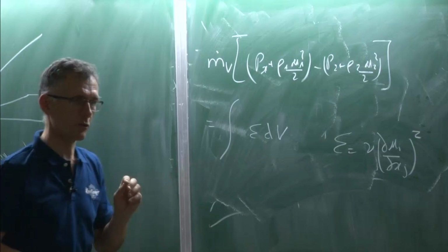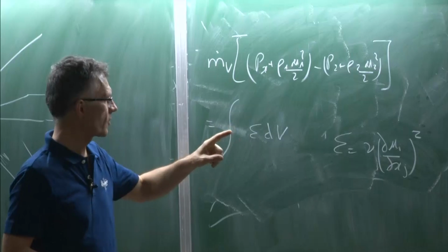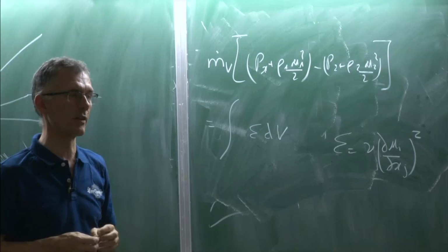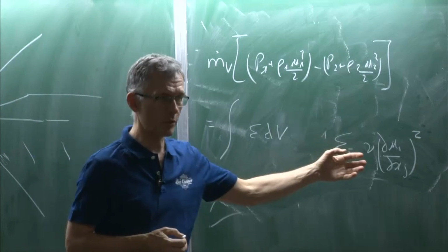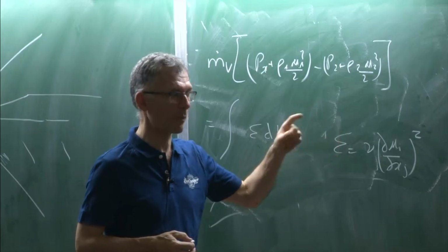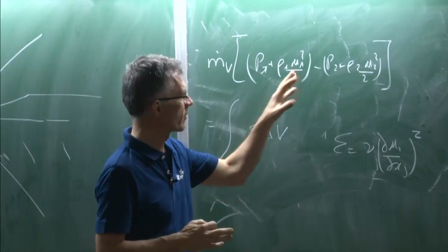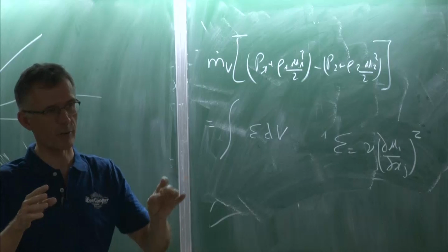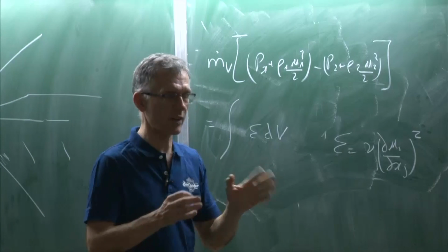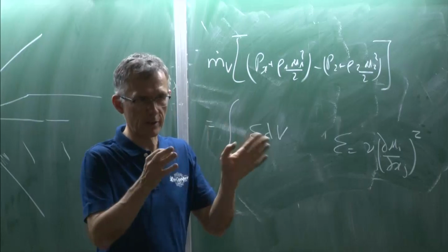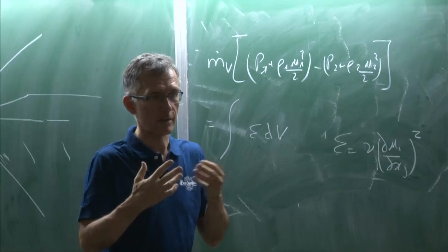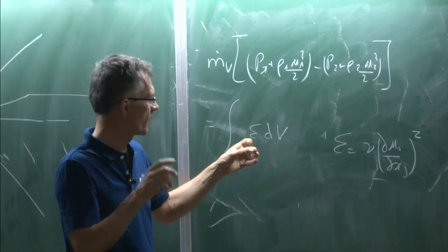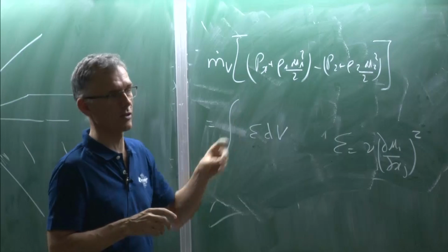And so the metric that you should use is epsilon. If you want the right pressure losses, the equation tells you that the field which must be resolved is the field of dissipation. And dissipation can be computed from the LES, and when we put points at the places where dissipation has strong gradients, then we get to 2%, 3% for the pressure loss. And the velocity field still remains very good. So it's really a good example that everything was in the mesh. If you can get the right mesh, then you get everything right. If you get a mesh which you built arbitrarily, then it's not working. Again, it's nice because it's telling you that the equation is useful. This thing tells you where to put the points if you're interested in pressure losses.